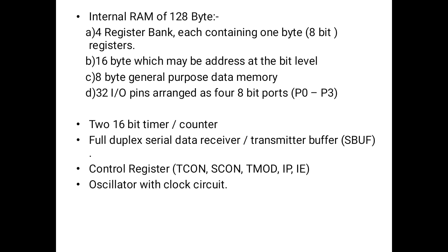It consists of internal RAM of 128 bytes in which there are 4 register banks. Each register bank consists of 8 registers of 8 bits. There are 16 bytes which may be addressed at a bit level. There are 80 bytes of general purpose data memory and 32 input-output pins arranged as 4 ports, each of 8 bits. There are two 16-bit timers and counters.